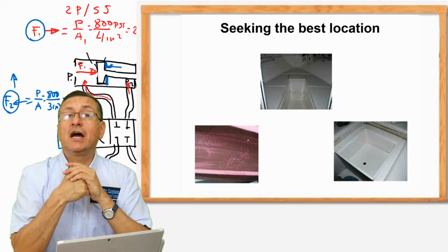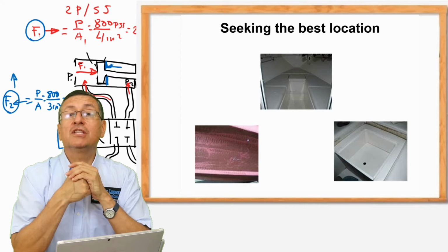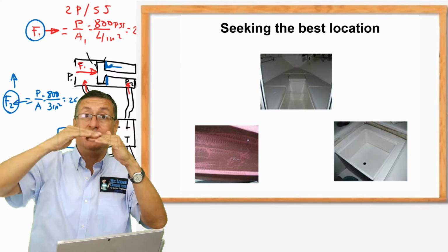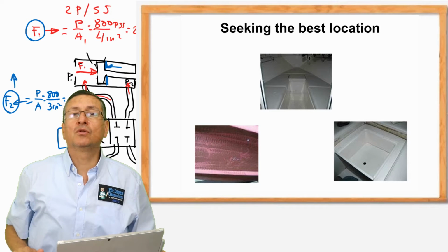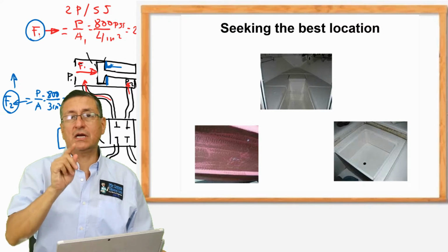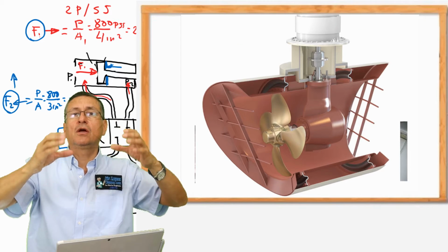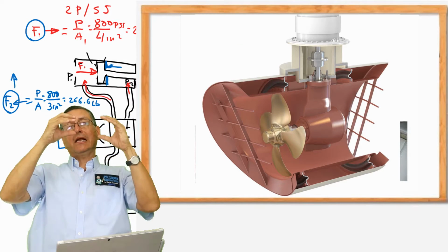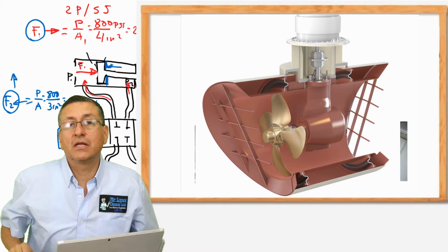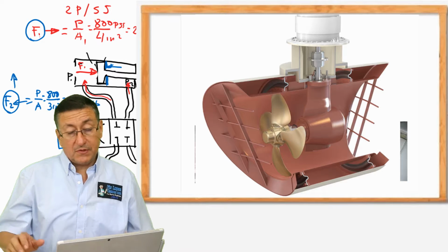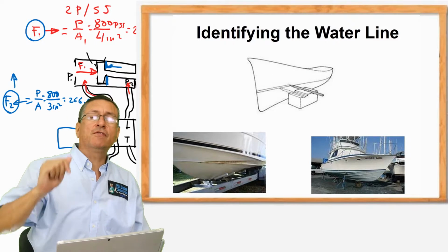Okay, you need to verify how much space, how much area that room has, and how much height you have to install the motor, because this is an important consideration. The motor can be installed vertical, horizontal, or inclined, depending on the room that you have in that corner, in that area. Alright, select the area and check outside of the boat.